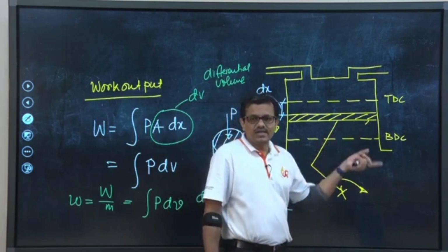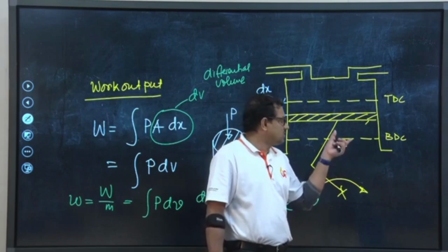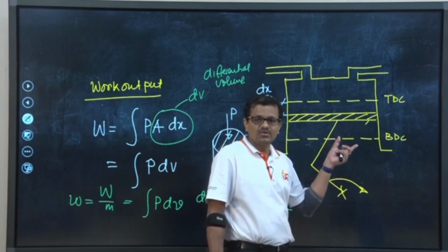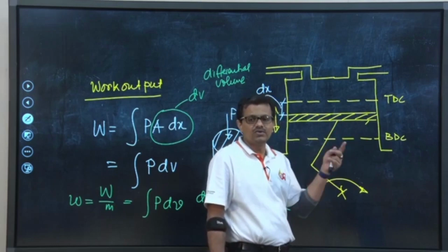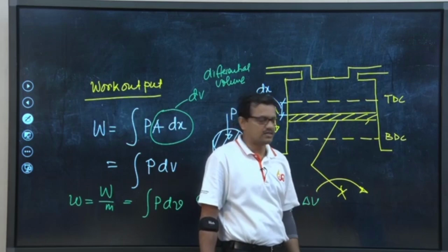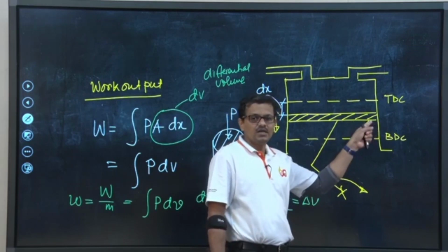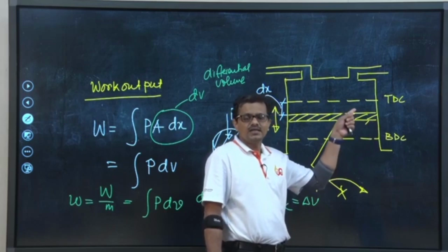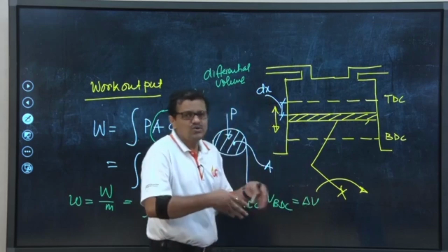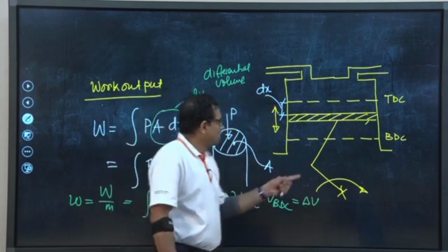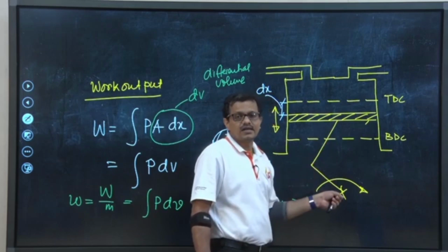To run all those units, some energy is needed. So, the parasitic loads include the amount of work which would be required to run all those devices. So, the frictional loss between the mating components alongside the parasitic loads, these two effects reduce the work which is available at the crankshaft.